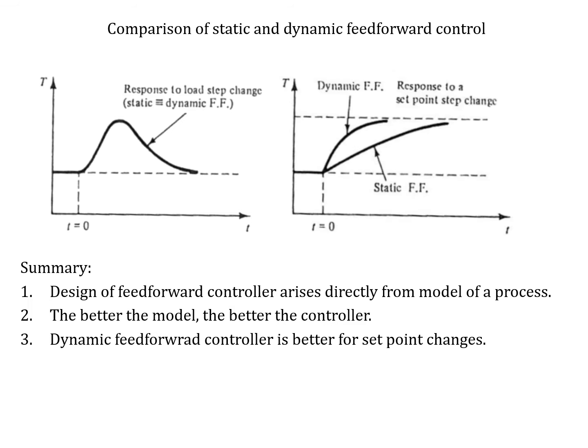So this is simple. And if you see how it's being done in terms of equation, in terms of the output, what sort of output you are getting for this sort of system, we can see that we have the feed-forward system. For load step change, the static and dynamic are roughly the same. Just quickly bring it down to the set point that we want. For the set point, the dynamic one goes to the set point, and the static one goes slightly slower to the set point step change.